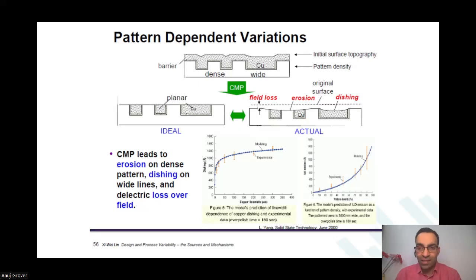You wanted to match the delays, na? But the wires have different RC now. The delays are not matched. Just because of the different surroundings, we can have different RCs. And this is a systematic variation. This is what we mean by structural matching: the structure of the layout in terms of density and everything should be matched. The bends that you see for one device should be similarly made for the second device also. Everything.